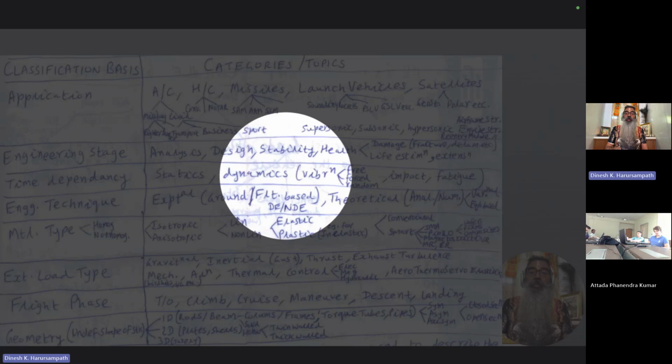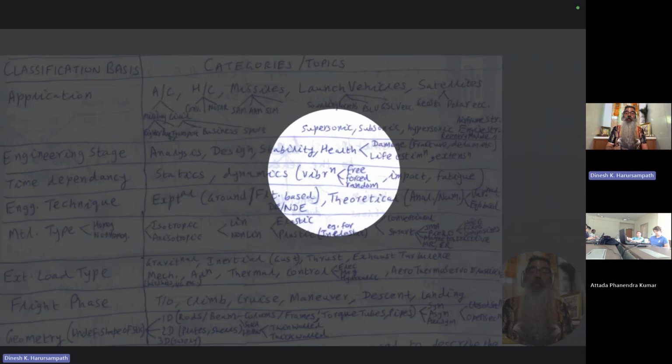Next, in terms of dynamics, again, it's the various kinds of dynamics or time dependencies that are involved. One aspect of it is vibration, which is essentially a motion happening in a time-dependent way. That time dependency can be caused by the overall structure itself, because of some disturbance that it has encountered, so that it's vibrating, what we call free vibration. Or it could be forced, in the presence of an external force or a moment, or force distribution or moment distribution, all of which in general we will just call by a single word, load, because of a dynamic load that exists externally. That's forced vibration.